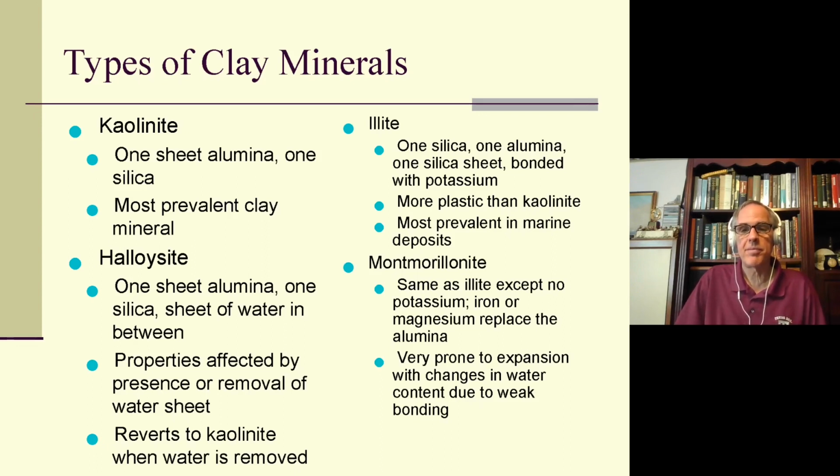These are your expansive clays. We're going to talk about this in foundations. These clays can be real stinkers to design and build on. If you have changing water content, they will expand. And when they expand, they can be very destructive.